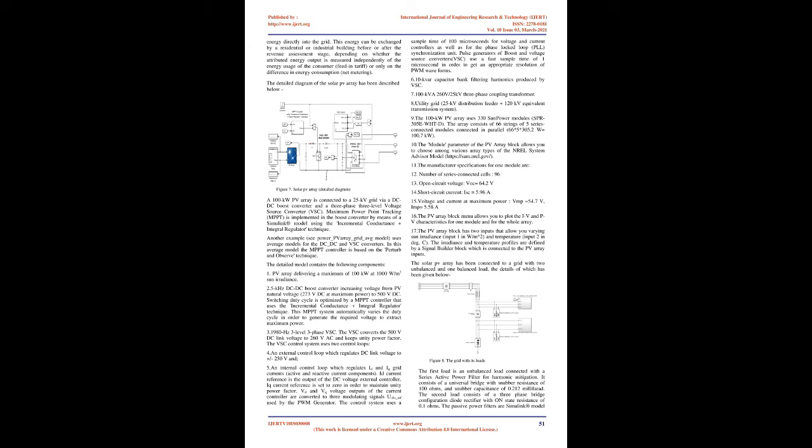Shunt active power filter. The voltage distortion in a weak system is very much dependent on harmonic current, while a stiff system of zero impedance will have no voltage distortion. Thus, provided that the system is not too stiff, a non-sinusoidal voltage can be corrected by injecting proper harmonic current.